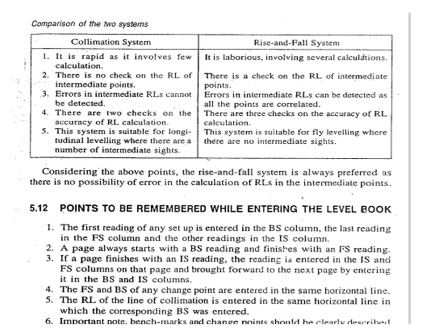Considering the above points, the rise and fall system is always preferred as there is no possibility of error in calculation of RLs at the intermediate points. Next, we are going to consider what are the points to be remembered while entering the level book.